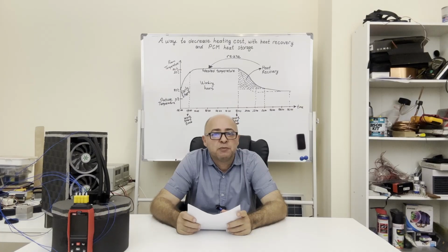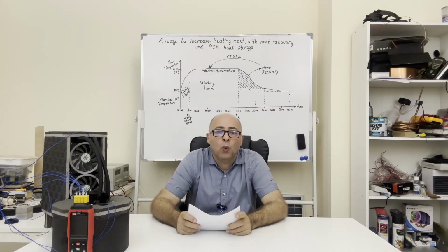The goal of this project is to cool and freeze the water in a tank with a heat pump during the heating of the room and to give its latent heat to the room, and after the heating period to remelt the frozen water by reabsorbing the heat of the interior objects of the room.